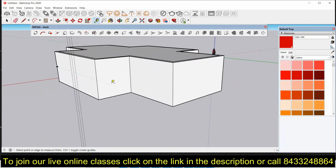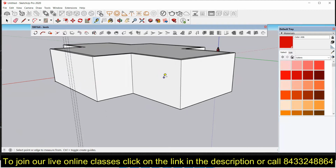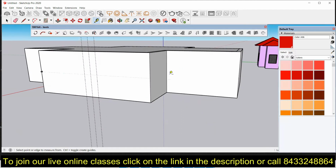Now next, let's make a window on this one. So for that I will again go to the midpoint, and let's make a window of 4 feet. So take a distance of 2 feet on each side. Also you need a lintel level, and that lintel level will be 7 feet, and then there will be a sill level that will be 2 feet 6 inches. So let's draw one at 2 feet 6 inches.